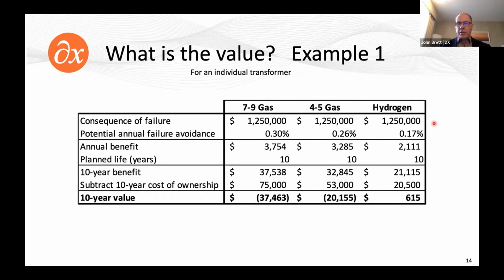If your organization has a policy of monitoring as much as possible, you shouldn't deploy a monitor on anything that's less valuable than $1.25 million. And you should just stick to manual DGA or pick a simple planned maintenance, preventative maintenance type approach, or even run to failure, which many do for very, very small assets.